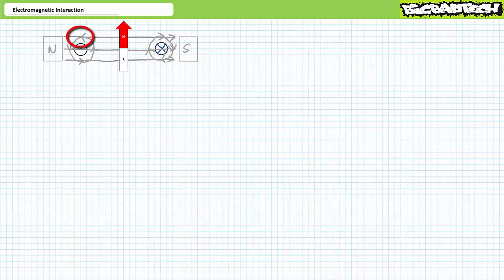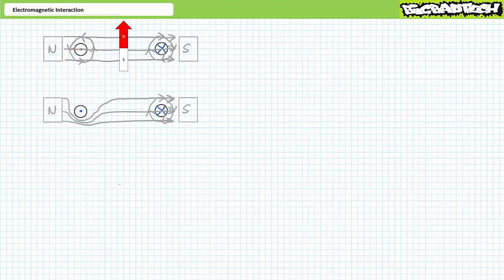Note the magnetic field on the top of the left-hand conductor is opposing, whereas the magnetic field on the bottom of the left-hand conductor is aiding. These magnetic fields coalesce such that there are more lines of magnetic force on the bottom and less on the top. Unified magnetic field below the conductor acts to push the left-hand conductor upwards.